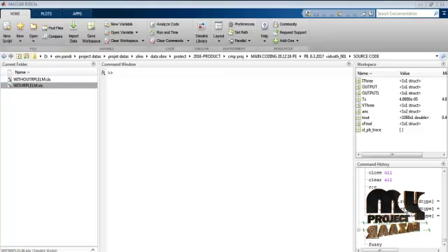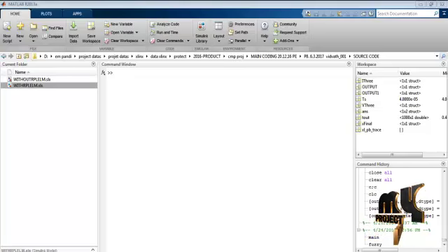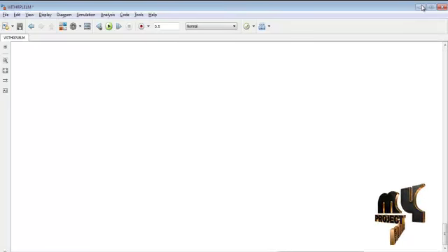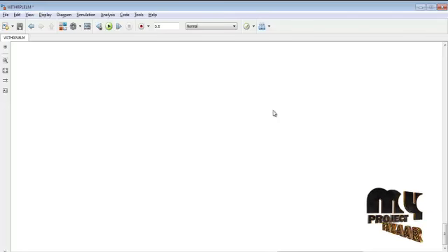Next, we see about the running process of our product. In this proposed implementation, the design is done in the MATLAB simulation environment. First, open a new model file. After opening the new model file, the main window will open. Then the elements are taken from the Simulink library browser. From the library browser, two main blocks are used. One is the SimPowerSystems block, and another one is the commonly used blocks.